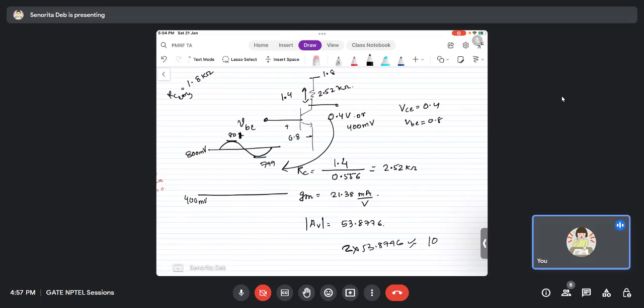So now you see this is going to 508, and this is going 400 minus 108 or so. And VC becomes less than VB, so the amplification action will not be there. This will not look like a sinusoid. It will clip off, because it is no longer in the active region. So this is what voltage swing or headroom is.